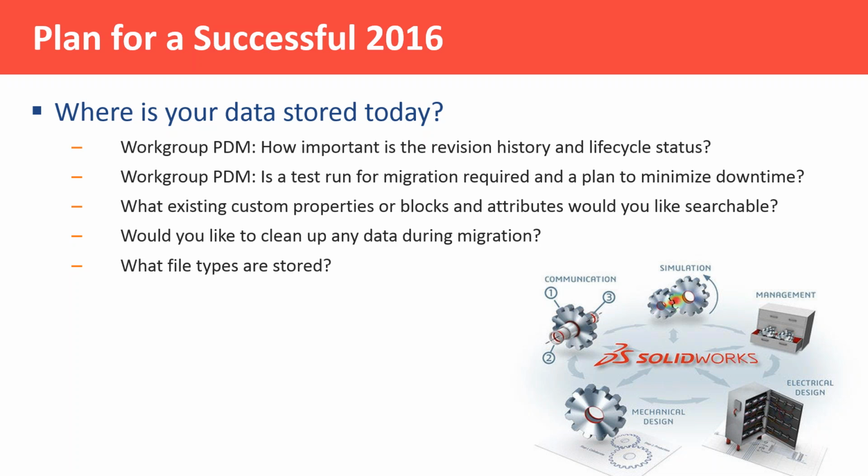Other things might simplify it too. In the past we've always done test run migrations and planning and checking of data beforehand. It takes time, and in reality it's very rare that anything major comes out of that. So you might just say, let's do a cutover date, transfer it over, and if there are errors, we fix them within PDM Standard or Pro on the other side. Errors are much less likely if you simplify what's brought over. The errors are usually related to something subtle in the history or life cycle, if you've changed how you used Workgroup compared to how it was set up when it was first installed.